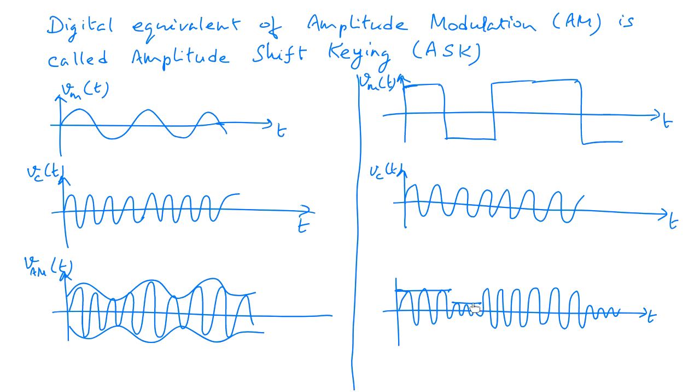So there are two voltage levels for the modulated carrier, depending on whether the information being transmitted is a 1 or a 0. Therefore this will correspond to 1 and this corresponds to 0. So that's a 1, that's a 1, that's a 0. So that's our bit duration, right? That interval is our bit duration, okay, which we simply can call TB, which is equal to 1 by RB, the bit rate, right?